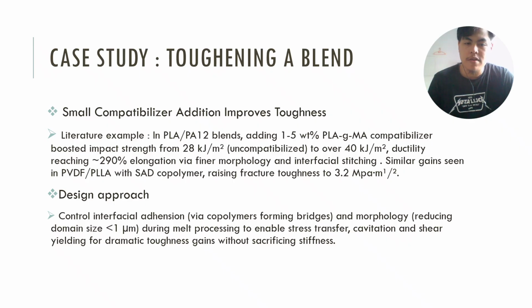For the design approach, control interfacial adhesion via copolymer forming bridges and morphology, which reduce domain size lower than 1 micrometer during melt processing to enable stress transfer, cavitation, and shear yielding for dramatic toughness gain without sacrificing stiffness.